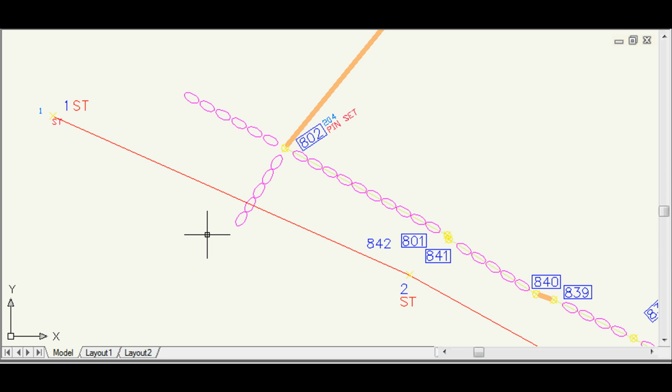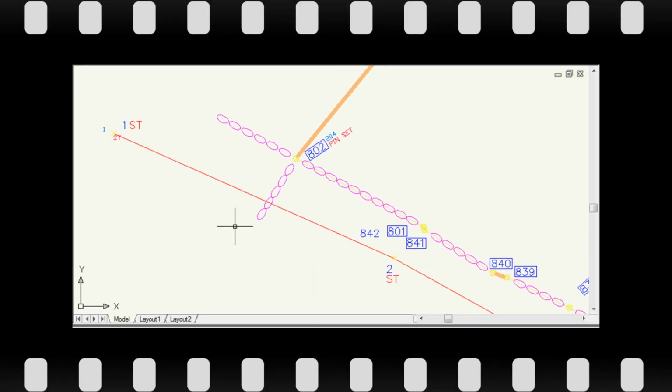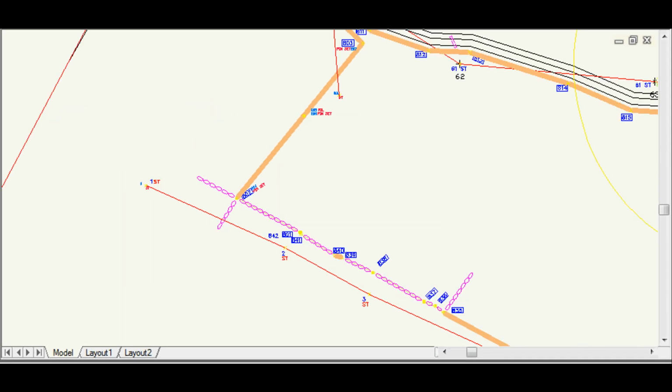Spring especially is bad because in spring you have frozen ground and snow and the sun coming out. So you set up a tripod on frozen hard ground and the sun hits it. And next thing you know, the ground is softening and melting. The tripod goes out of level. So that's the basic explanation of that.